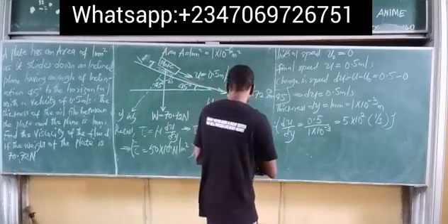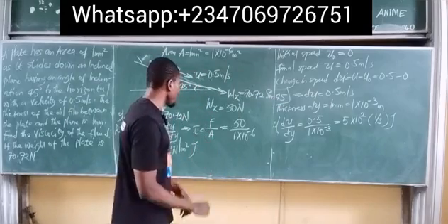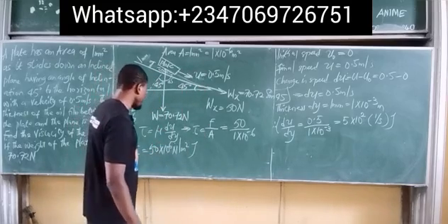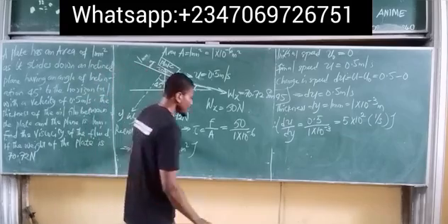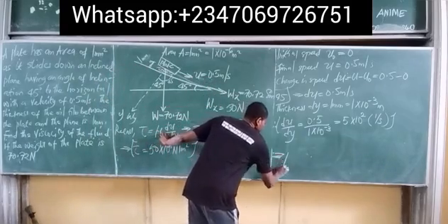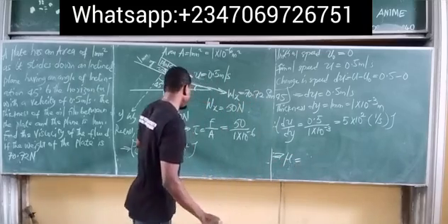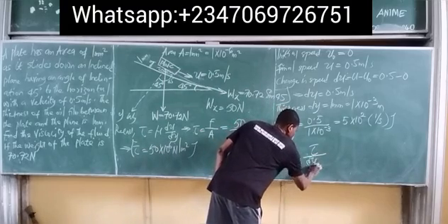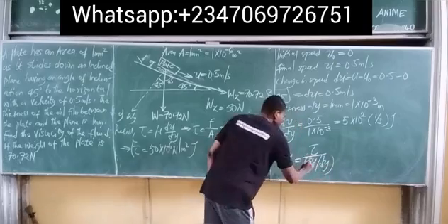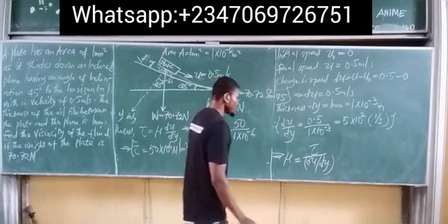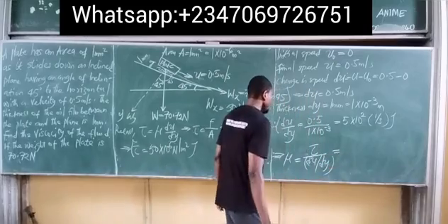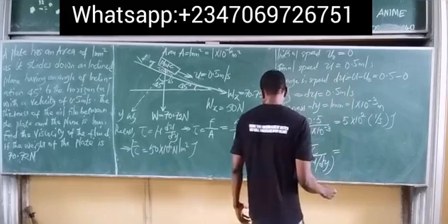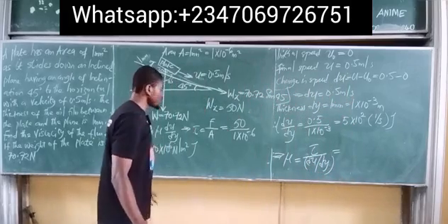All right, so having this now, from shear stress equals mu du dy, we can actually make mu the subject of the formula. From here, this simply means that dynamic viscosity mu is simply the ratio of shear stress all over du all over dy. So this gives us dynamic viscosity. This is equal to the shear stress value, which gave us 50 by 10 to the power of 6.